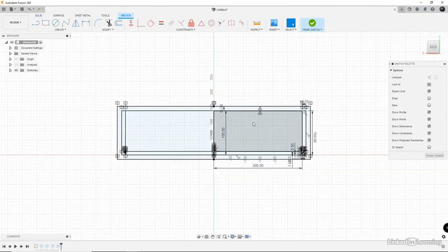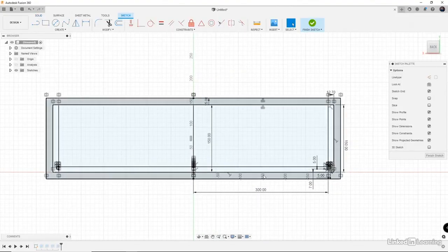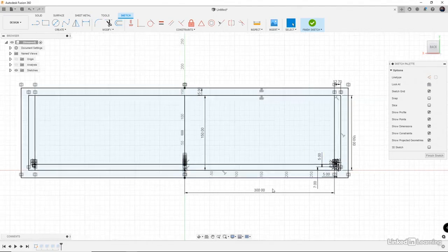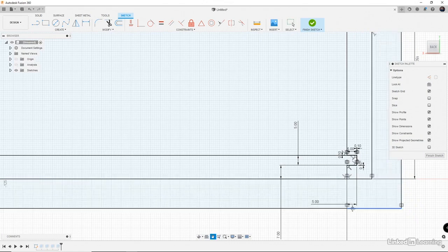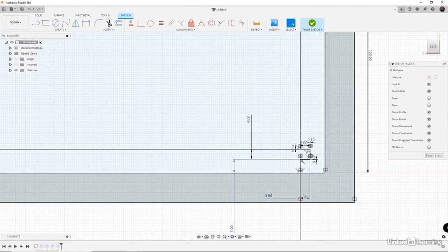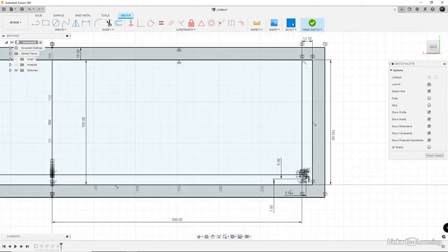You go into the sketch here and it looks pretty simple. You'll notice that I built it on the mirror of the origin, and then I basically created the entire sketch on one side. So this is the one side of it that I created and then mirrored to the other. The reason I did that is just so that it's all updatable. So I built this, and this is the front overhang that I built, the face of the drawer. And I did this by using an offset. So this is updatable. So I can just literally come over here.